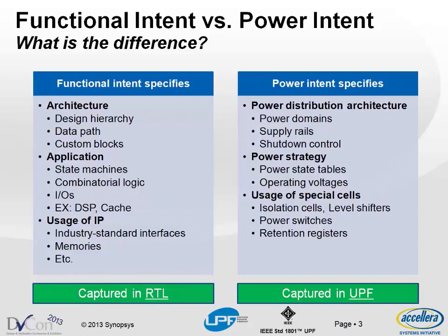They worry more about, oh, this trace won't meet here. For RTL design, we worry, does this functionally work? But for some of these things, we need to bring some of this information forward into RTL design to properly model how your design works with this power intent. And there are things for power strategies. Exactly what are the states of your design?